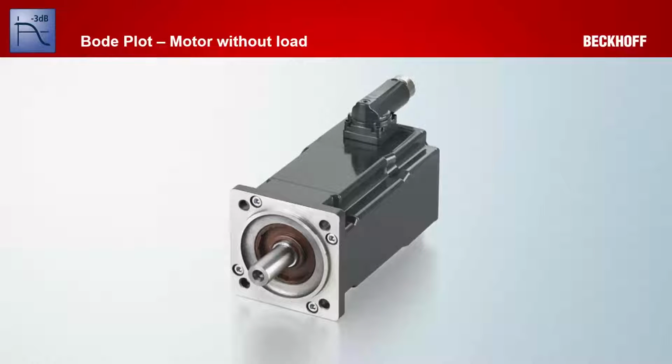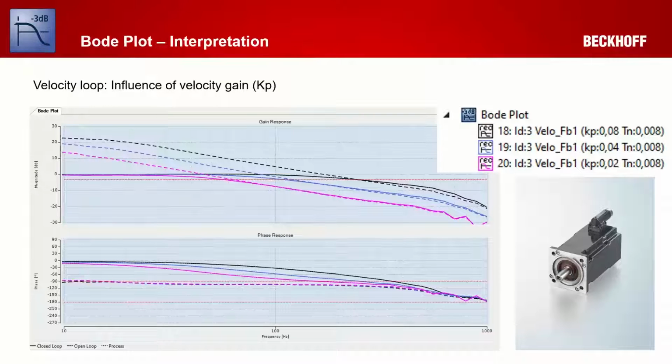We will start with a motor without load, so an empty motor shaft, to see how a Bode plot looks for an empty motor. Here's the curve, or in total there are 3 curves. We go through this picture step by step. The first graph shows the gain response. This is the ratio of the actual value divided by the set value.